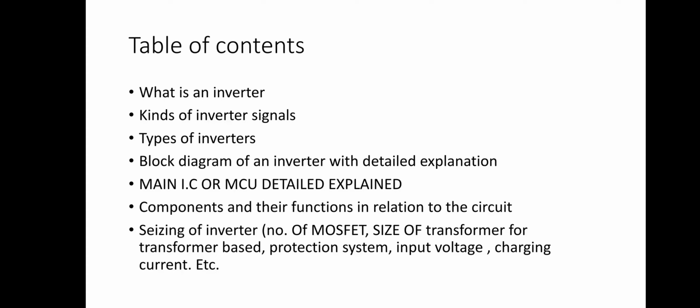Then protection systems like low battery cutoff, over voltage, reverse polarity, short circuit, then overload, and the battery full system too. These are the protections we'll also be checking in this system, how to design them and how to apply each and every one of them.